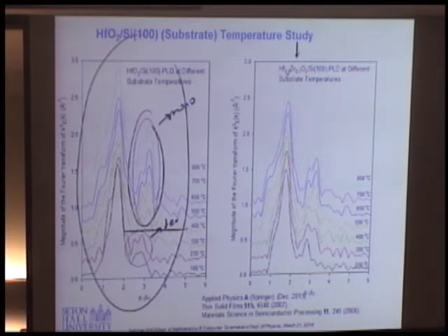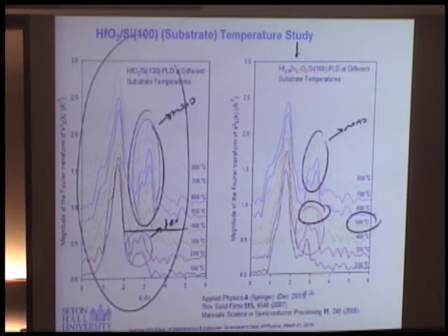Now, if you put zirconium, you delay this thing. All right? You go to the 500 degrees. So there's a big difference. This is the tetragonal. That's the monoclinic. Okay. So you can tell, hey, 100 degree difference. That's a big difference for them. Now they can process at 500 degrees, still get to the tetragonal phase. That's a big thing, all right? So by just putting, that's my hunch, Intel is just putting zirconium and things, make the film more stable, durable to the processes, okay?